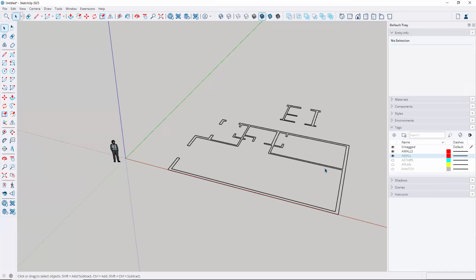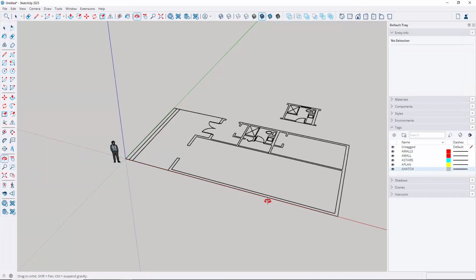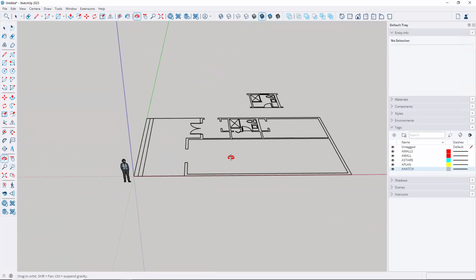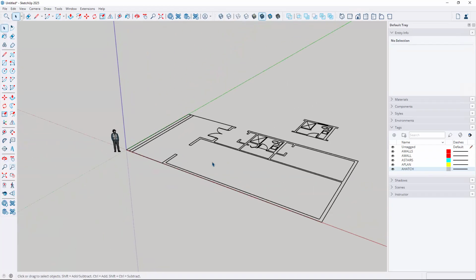And this is helpful to be able to still control my layers. In SketchUp, they're called tags. To be able to control that in SketchUp. So I'll turn them back on so we can take a look at everything that's there. So that's what you need to do. Once you've brought that in, make sure you save as, and you're going to save this and simply call it building. That's all. And look at the specifics as to what it will be called. Make sure you save it back to the appropriate drive, and then you can begin to construct.